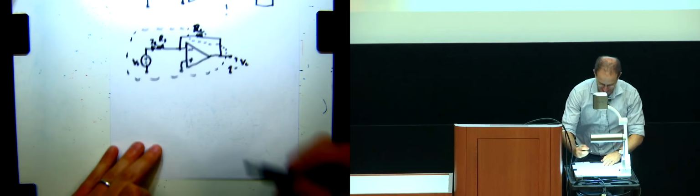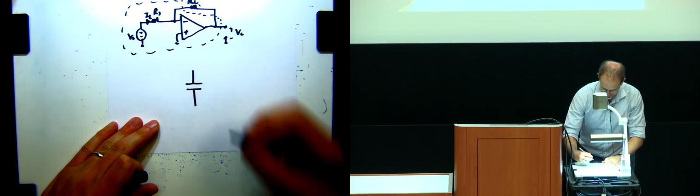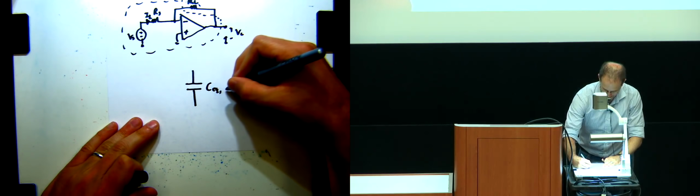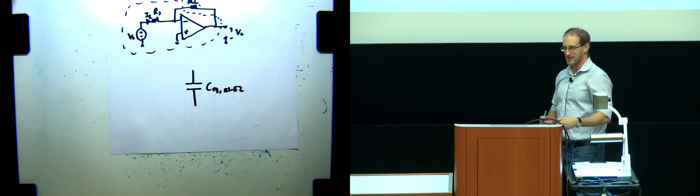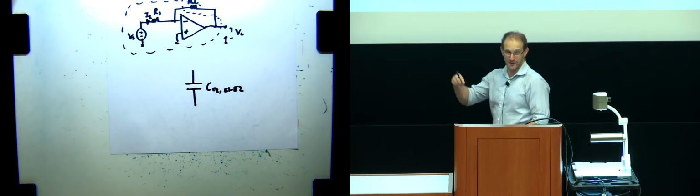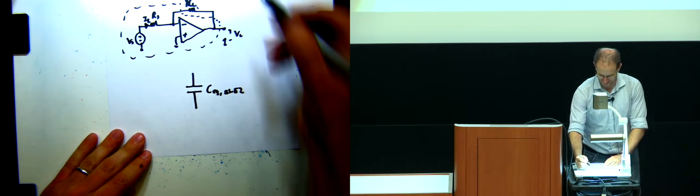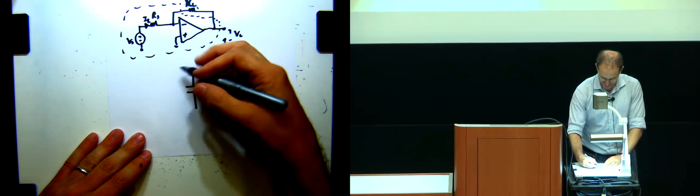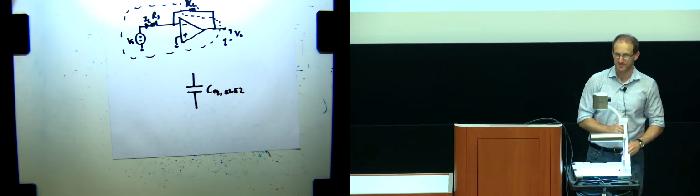So remember, the whole touchscreen sensor, at least the latest one that we looked at, was all based on some equivalent capacitance that was going to be changing as a function of whether or not your finger was pressing, right? And so indeed, rather than connecting a resistor, what we're going to end up doing is taking this quote-unquote current source and connecting it to a capacitor.